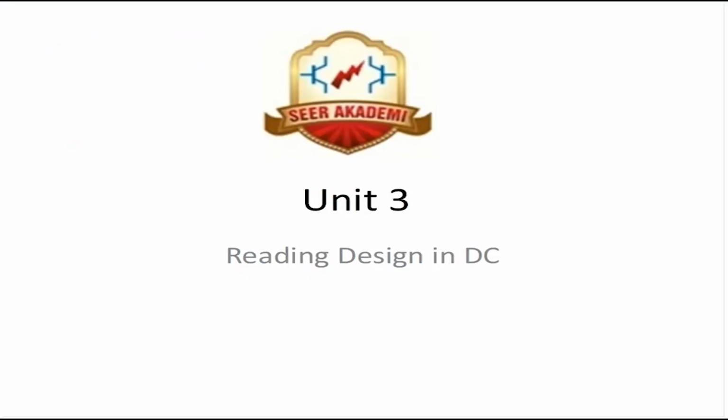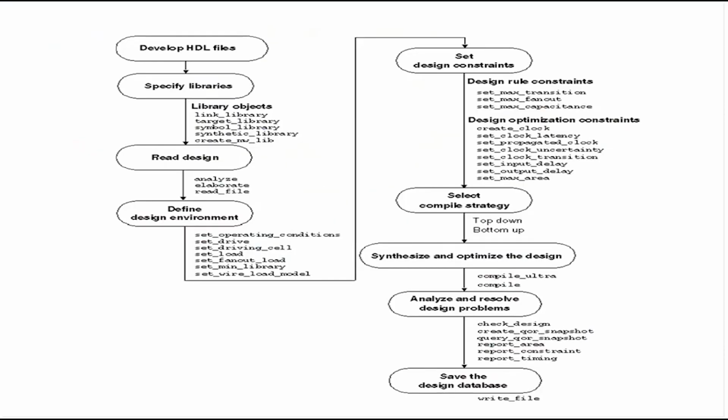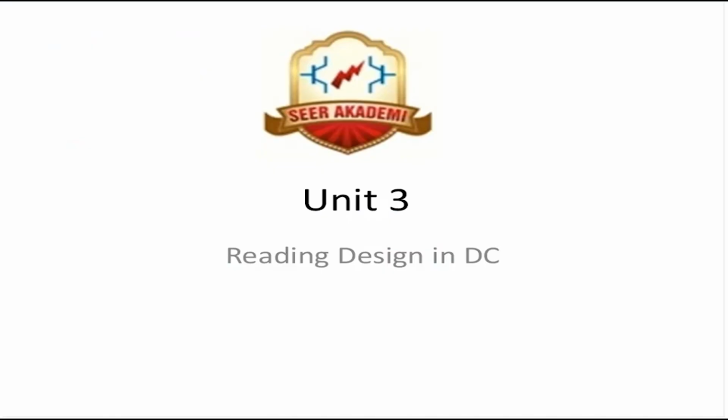So during the last session, last lecture, we looked into how to code, the important points regarding RTL coding in Verilog. Now in this section, assuming you have the RTL files prepared, I'll go into how to read this design into Design Compiler, and what to look out for.